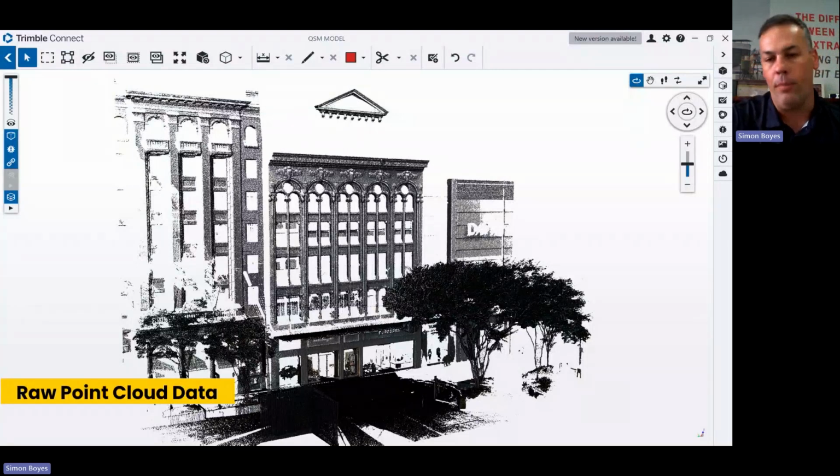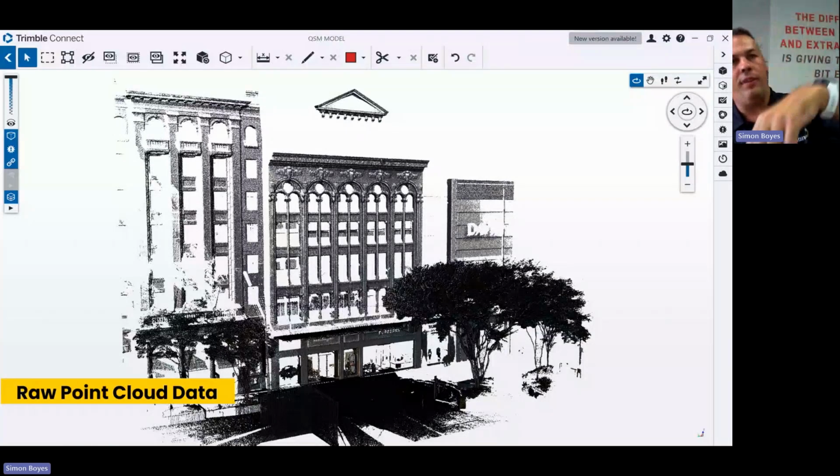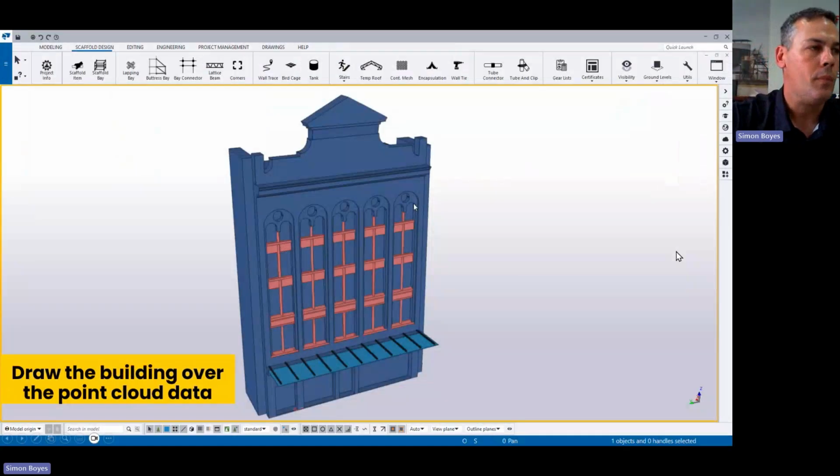Because we scanned that from the ground, and you'll see a little bit further in the model, there's a lip that comes out off the top of this building here. So the laser couldn't shoot past there to get that. So what we do there is, I'll show you again in a sec how you can capture that. But what you do is you move the scanner from place to place, and then again, line of sight, it'll be able to shoot different angles.